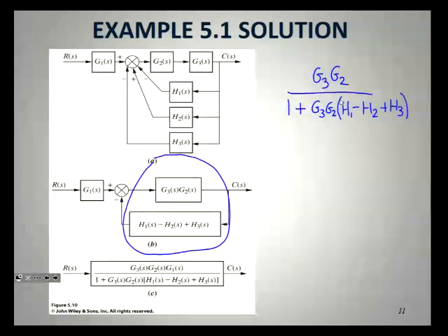I hope that's really obvious. It's not too difficult, really. That's just your G over 1 plus GH. And then this multiplies everything. So that goes on the top line. That's like a numerator multiplier. So then you just have G1 times everything else. That's kind of obvious. So if you ever see this in an exam, just leave this bit right to the last, and then that just multiplies the transfer function. That's an easier way of doing it. Is that all right? Follow that okay?